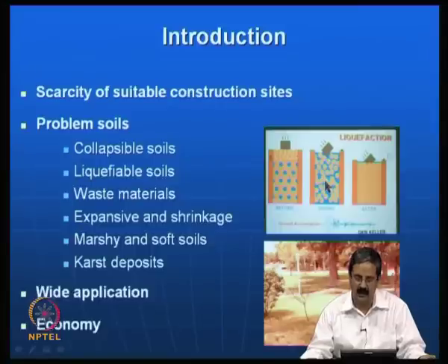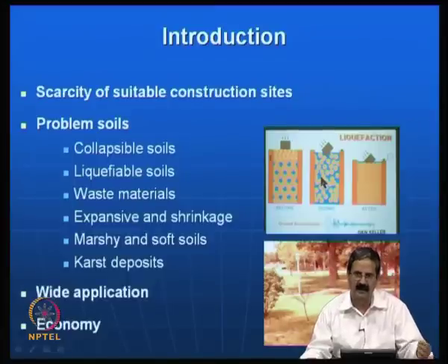In fact, we can call it a quicksand condition also, which is nothing but static liquefaction, meaning the soil behaves like a liquid when the effective stress is 0. When the effective stress is 0, the soil loses all its strength and behaves like a liquid. So, these two soils, collapsible soils and liquefiable soils, are problematic because it is very difficult to have foundations on these deposits.